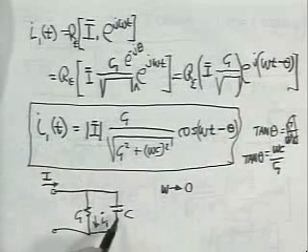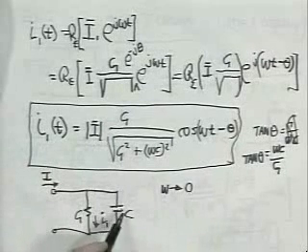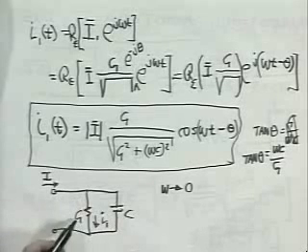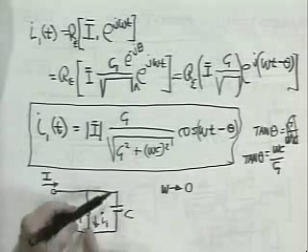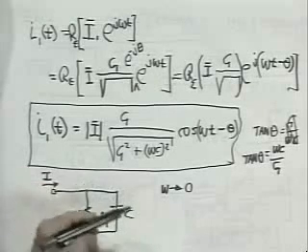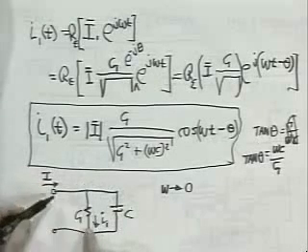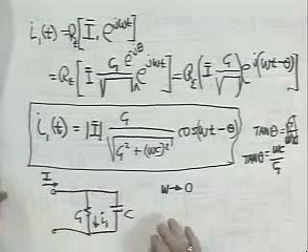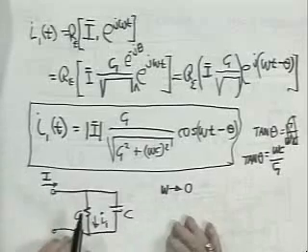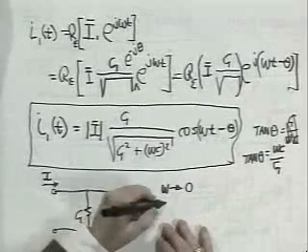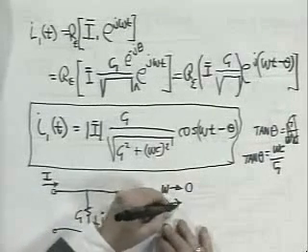That makes sense, because as this impedance gets higher and higher, the current sharing ratio changes, and more of the current flows through the conductance. If these were two resistors, and I said, how does the current in this resistor change as I make this resistance larger and larger, you wouldn't hesitate to say it gets bigger and bigger. Eventually, when this becomes an open circuit, all of the current is flowing through the conductance. So the sanity check, in terms of dimensions and in terms of asymptote, at the low frequency end at least, checks. Suppose I look as omega becomes very large.